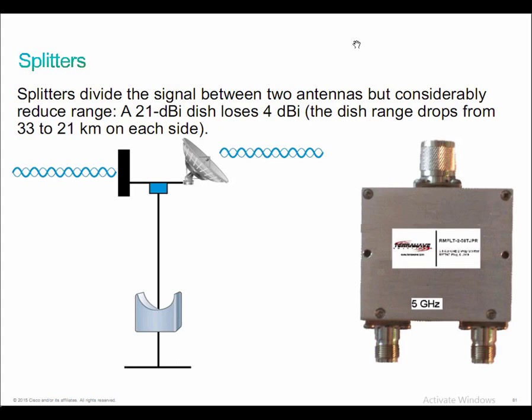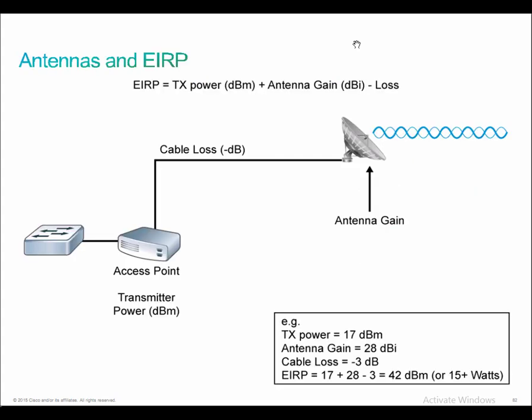The last concept we've already kind of talked about, EIRP. And this is something that you guys will have to calculate on the exam as well. But keep in mind, from a production standpoint and from an operational standpoint, the total EIRP, or the transmit power, is governed by whatever governing body exists in your particular region. In the United States, it's the FCC.